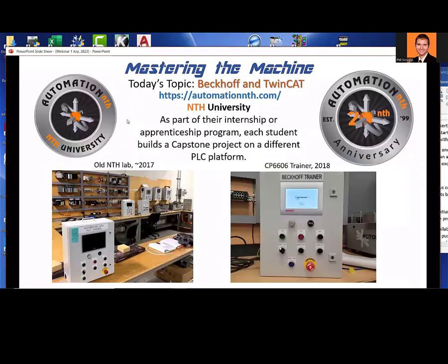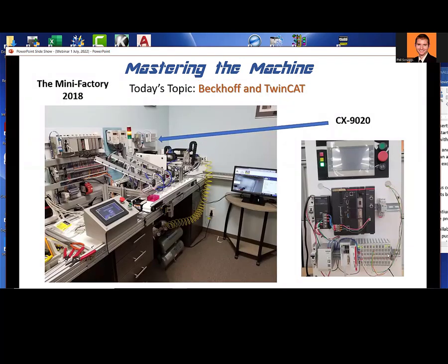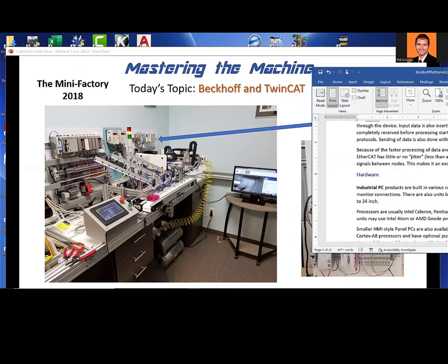There we go. So this platform is a 7-inch panel PC, right? This is an example of one of those multi-touch touchscreens that this student did on the Beckhoff trainer. All the I/O and everything is controlled via EtherCAT out of the back of this. I have another picture of it if anybody ever wants it, but it's running a bus coupler inside of it with some of the same type of I/O that I have here, right? So this I/O can be stuck on a bus coupler or on the right of an embedded PC.